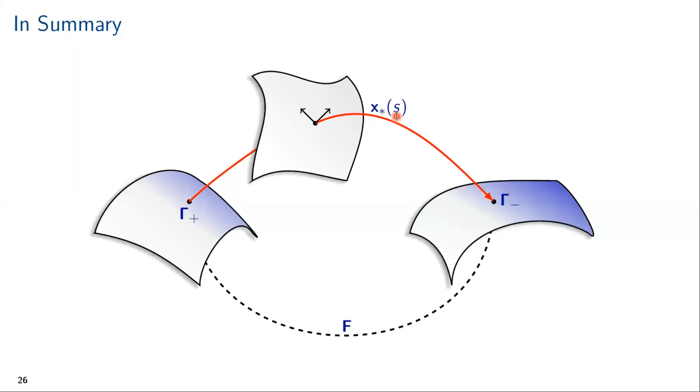Now we showed that this could reduce the dynamic constraints of the system down to only a few first order differential equations, the number of which equals the degree of underactuation, and which then let us state a quite efficient to solve trajectory optimization problem, which could give us a trajectory as desired, and which could be used to find a walking gait for a robot with 3 degrees of freedom, but only a single actuator.